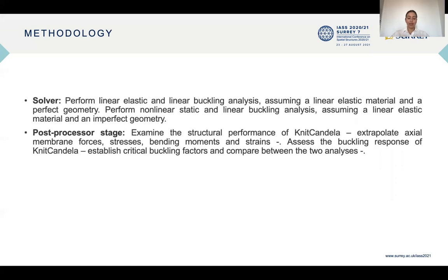Moving forward, linear elastic and linear buckling analysis were performed assuming a perfect geometry. I then performed a nonlinear static analysis considering P delta effects. The stiffness of the model established at the end of the nonlinear static analysis was considered when executing linear buckling analysis. By doing so, geometric nonlinearities were considered. Once both analyses were executed, an order of magnitude of the computational results was established in order to ensure that the results obtained are reasonable.